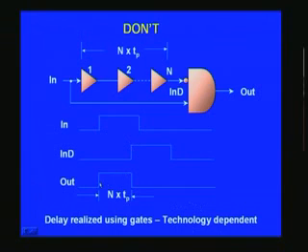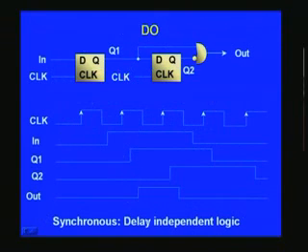So the way out here is, if you are interested in just creating a single pulse as such like this, what you can do is have two flip-flops, and input is applied here, and it may appear at any point of time. So let us say it appears here, and there's a clock here, and we are going to reckon the whole thing on positive edge basis.